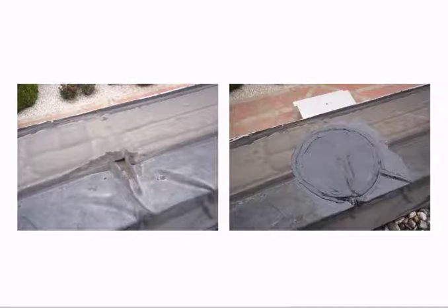One of the things that you've mentioned quite a bit, Craig, is a lot of the prep work. I've heard you talking about primers, solvents, cleaners, all that. Sometimes it seems like we see good solid patches being put on, but that prep work has been lacking up front, and that's just not working out long term. Your prep work is the key ingredient to a permanent long-term patch. If you don't clean your surface, if you don't prime your surface, if you don't take the extra measures to perform that, then your patch will fail, and you'll be back out there again making that same repair.